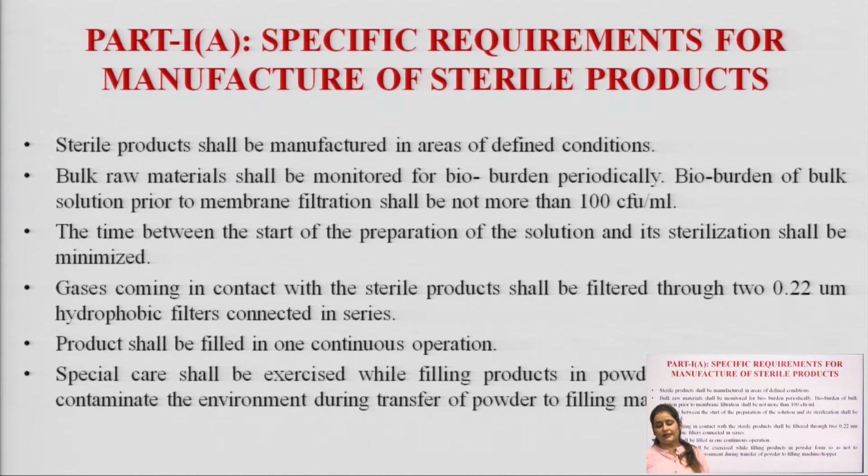Bulk raw material shall be monitored for bioburden periodically. Bioburden of bulk solution prior to membrane filtration shall be not more than 100 CFU per ml. The time between the start of the preparation of the solution and its sterilization shall be minimized.